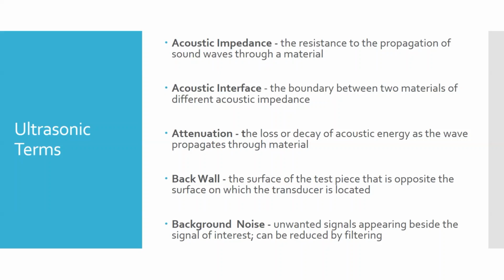Can also be materials that are bonded together if you have multiple layers. One of the Saab 340s I worked on used a bonded metal skin. They had actually 2 or 3 layers of thinner aluminum that were bonded together to create the skin. We would have to do ultrasonic testing after they got damaged to make sure that there wasn't delamination or disbond between those different metallic layers. And then they were also bonded to the ribs and the formers and the stringers instead of being riveted everywhere. And so if they got damaged, we would use ultrasonic testing to look for those disbonds that occurred.